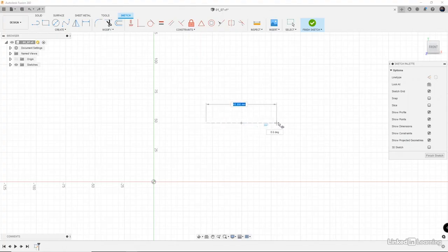So here we can specify the width of the ellipse. So we can specify the actual width, so like let's say 100 millimeters, and then we can also specify the angle. So let's say we can do 10 degrees. So I simply did that by, again, hitting the tab key so I can go between the two, and then just click right there, and then you can specify the height of the ellipse itself.